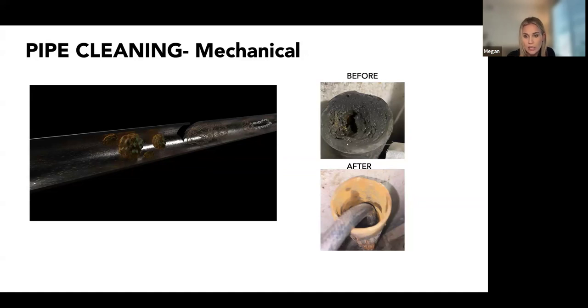So it's not actually being cleared out, and you'll see issues in another place not too long after you clear it. So again, you want to remove the debris, you want to vacuum it out. And also you want to start the cleaning from the bottom going up, so you're not going to cause any downstream blockages.